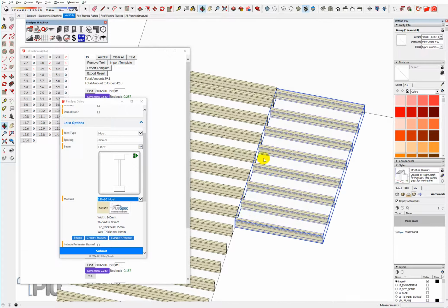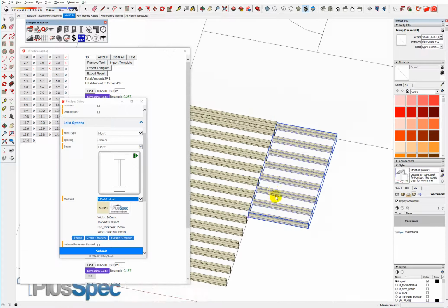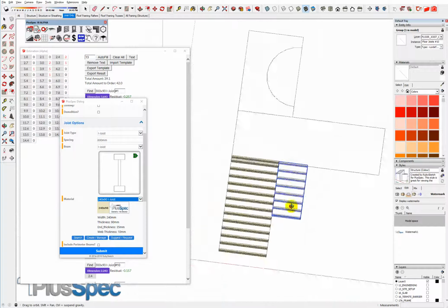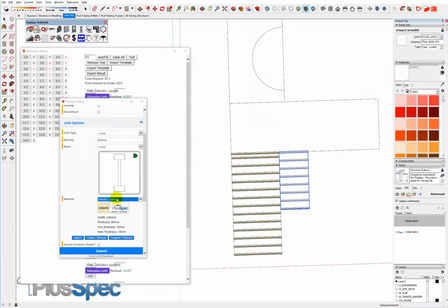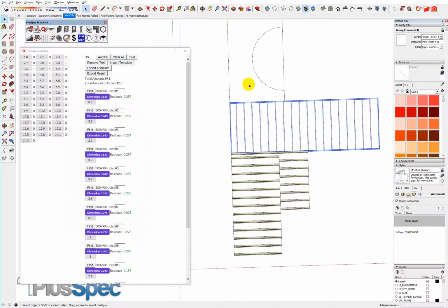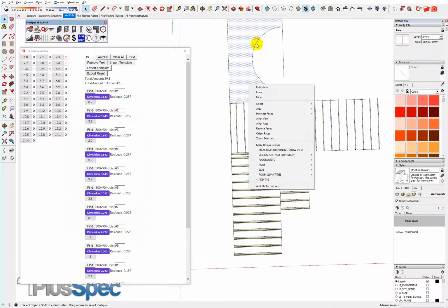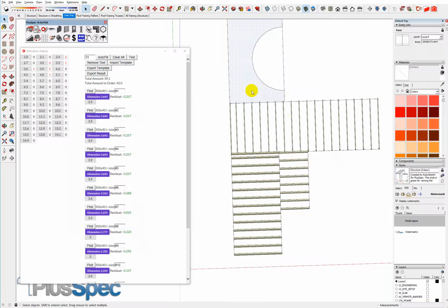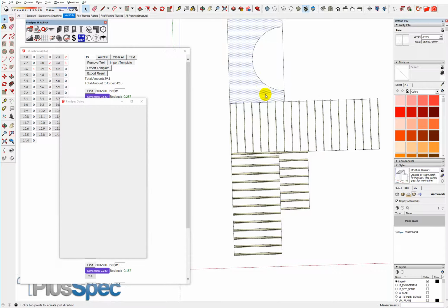And if I actually wanted to change the direction of the joist, or the spacing of the joist, I can do that. And I might say, okay, we're going to pop back up to our last size, and we're going to go here, here, and here. So we're at full height again here. And this one here, I'm actually going to run my joist around here. This would be a difficult thing to work out and probably take several hours to do. Create joists. I'm going to run my span this way.